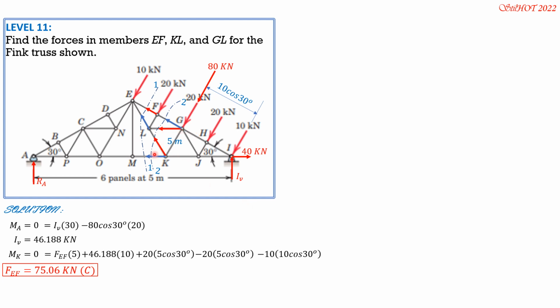Take note, there are four forces cut through this section, and only two have a common point of concurrency. Which contradicts the principle that if there are four forces, three must meet at a point. But actually, we can still solve this if the equation is not moment summation.